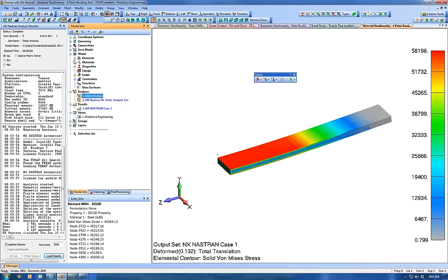All right, now for our material. There's two different ways that we can model plasticity. And the first way that I'm going to show you is to set up a stress-strain curve. Now, it's not my preferred method, but I think it's a bit more intuitive, and it provides some information about how we would set it up the other way, the bilinear way.